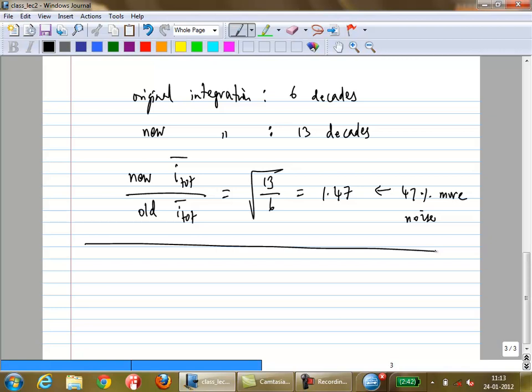Okay. So now let's come back to your thermal noise. You'll see that quite often one of the properties of this is that because it keeps going down with frequency, if you're really interested, let's say, in integrating noise from 100 Hertz to 100 megahertz, typically what you'll find is 1/f noise will not be a major portion of the noise, because beyond your 1/f noise corner, your 1/f noise goes below your thermal noise floor, and you're going to be integrating thermal noise which is much larger. In a typical broadband system 1/f noise would be of less concern than in a narrowband system, okay.